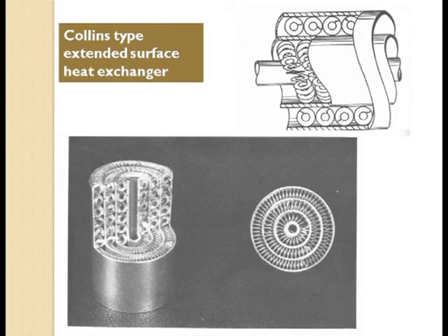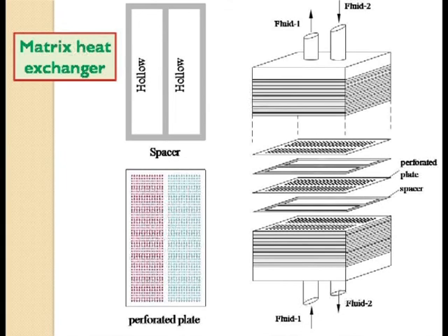But as you go to the next one, this is also a heat exchanger. Basically, it is also tube in tube. You have a large number of tubes, say tube 1, tube 2, tube 3 and tube 4. But in between the tubes, instead of soldering them, you can put this type of helical ribs, so that these ribs will be in contact with this tube and this tube, and in between the ribs you can pass the fluids. Therefore, heat transfer from this fluid to this fluid will be transferred across this wall, as well as these ribs or helical ribs will act as fins, so that faster heat transfer will be there from this fluid to the wall, then from the wall to this side, this fluid. So like that this is a somewhat improved heat exchanger, and Collins used it for its liquefier.